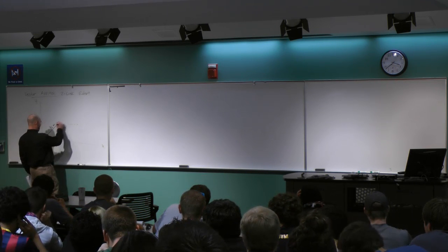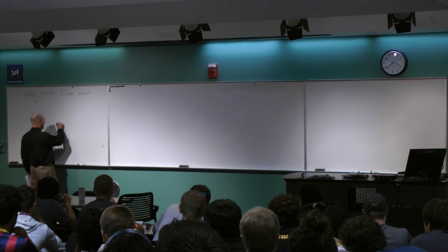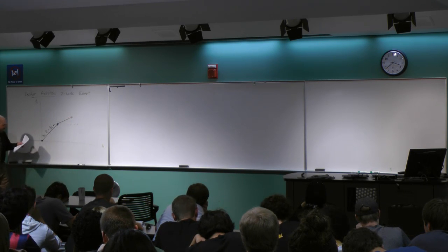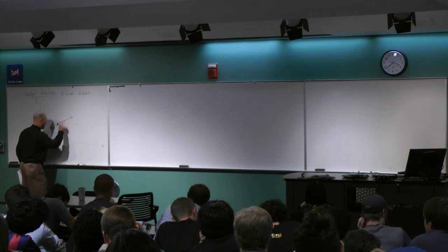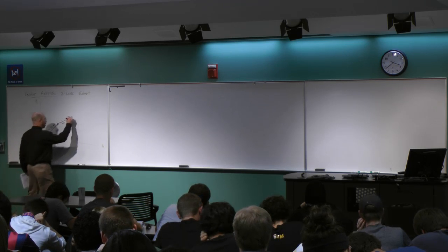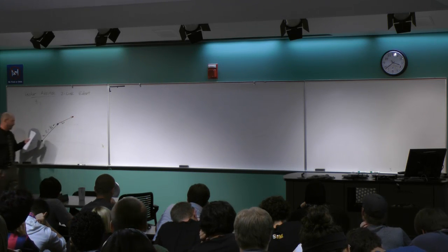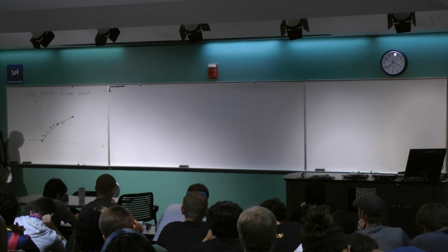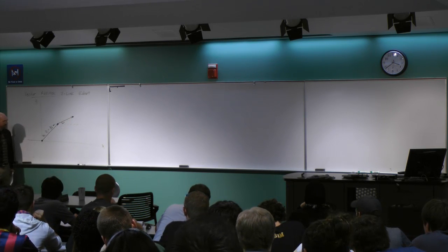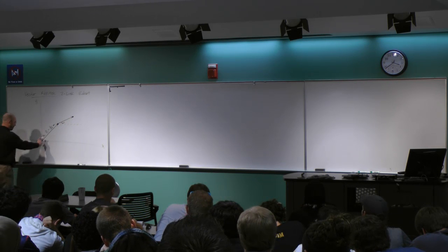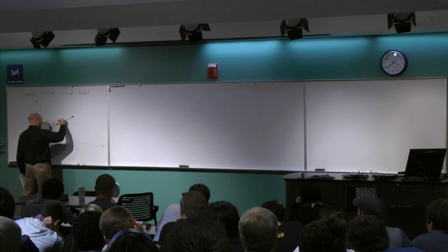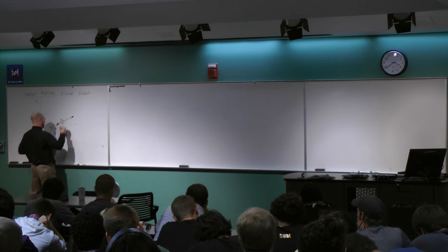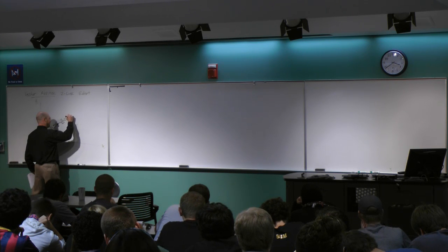Not a bad idea with vector problems to do things semi to scale so it makes physical sense. And I'll say this one's at an angle of 30 degrees relative to the horizontal in this case. I'll go ahead and locate that here. So that's 30 degrees there, and here's the tip right there. Here's the idea. I would like to represent the final position of the end of the second link with a single position vector from the origin. So I've got P1 at an angle 45 degrees, then I've got P2 at an angle 30 degrees. This guy, we'll say it's 0.5 meters.